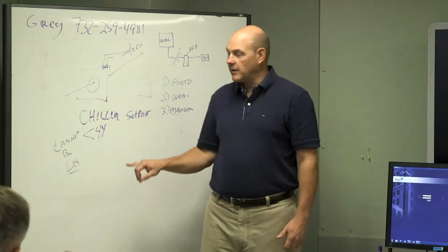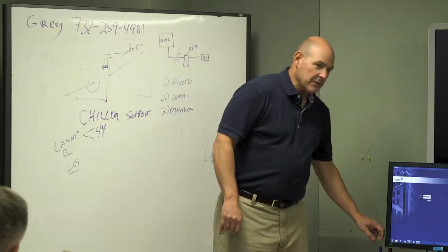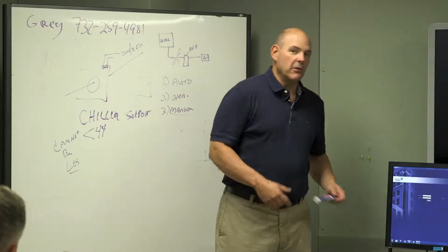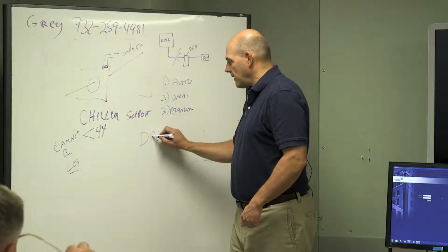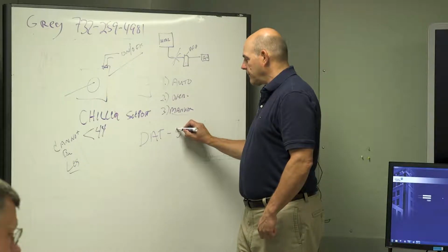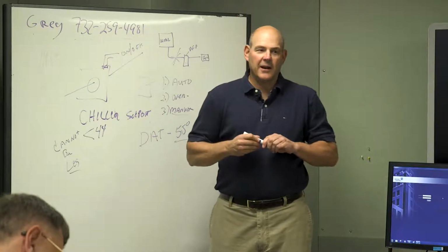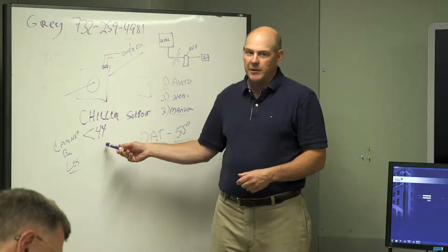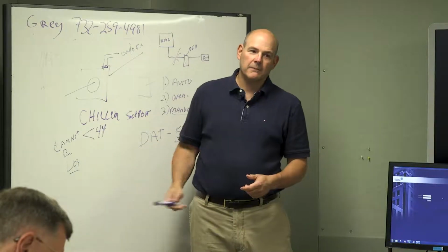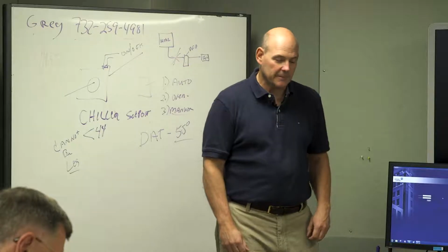You know, if you want to make it 48, 50, because don't forget, the air handlers downstream really want to discharge what we call discharge air temperature of 55 degrees, right? So if the outside air temperature is 60 something and you just need to knock it down a little bit, you really don't need 44. But that's, again, for another day. That's looking at plant efficiency.